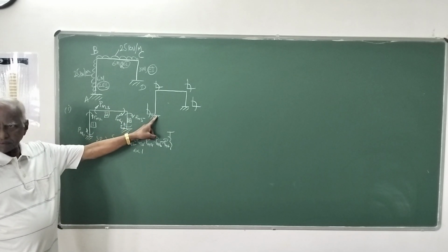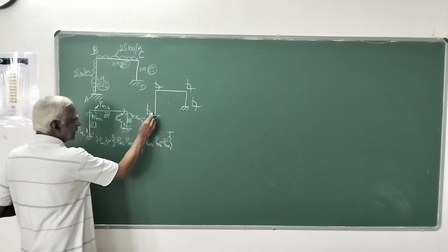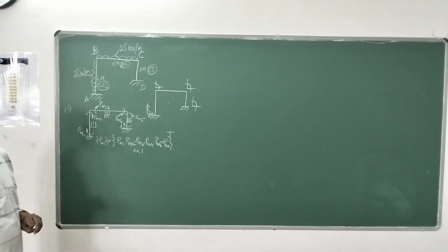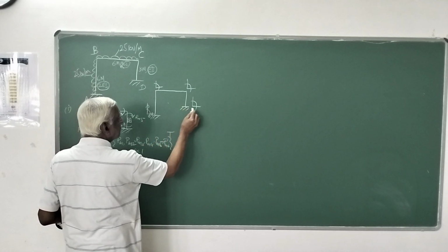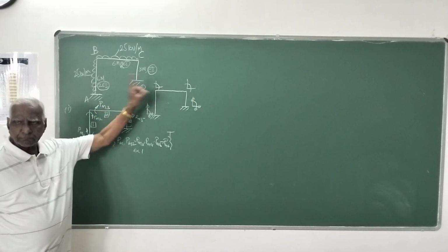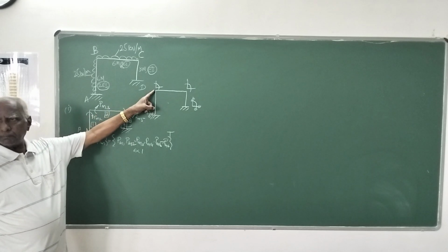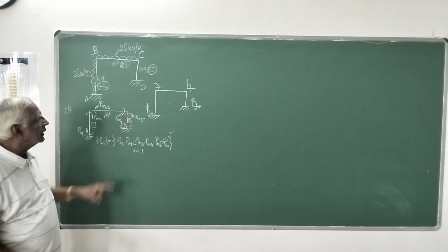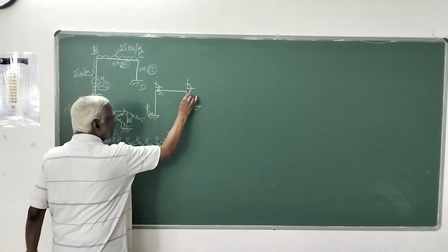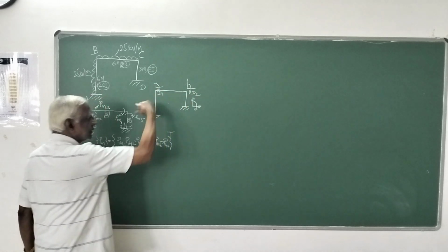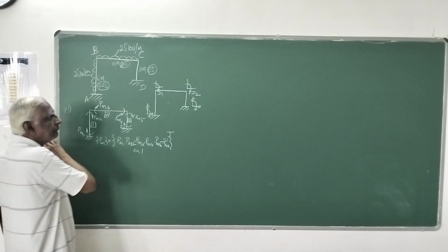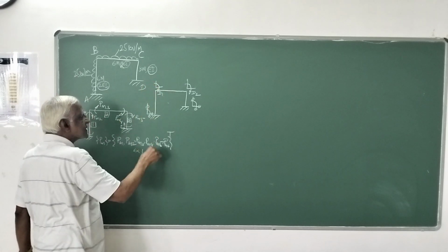So here at the joint A, no displacement is possible. All displacements are 0 in the global coordinate system. Here also at joint D, no displacement is possible. At B and C, the displacements are possible because it is a continuous end. So first I will mark the rotations D1, D2, that is the rotation at B and the rotation at C, that are the unknowns.